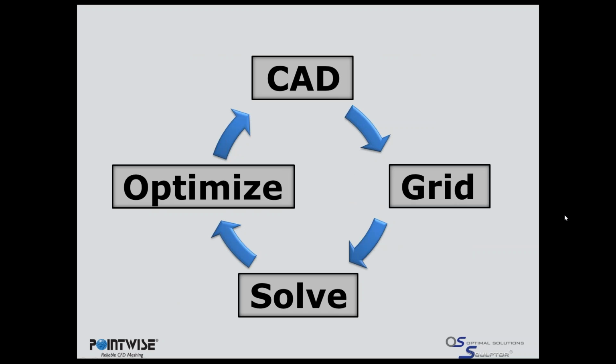So today we're going to be talking about optimization and how to prepare grids for optimization. This is the typical optimization workflow where you generate CAD in a CAD package and you parameterize it. You then pass that on to a mesher. You generate your mesh, you pass it on to a solver, which will compute your objective function value, and then pass it on to an optimizer, which would suggest changes to the parameters that would regenerate the geometry. Then you go and regenerate the mesh and then resolve. And you go through this loop over and over again for each new design.